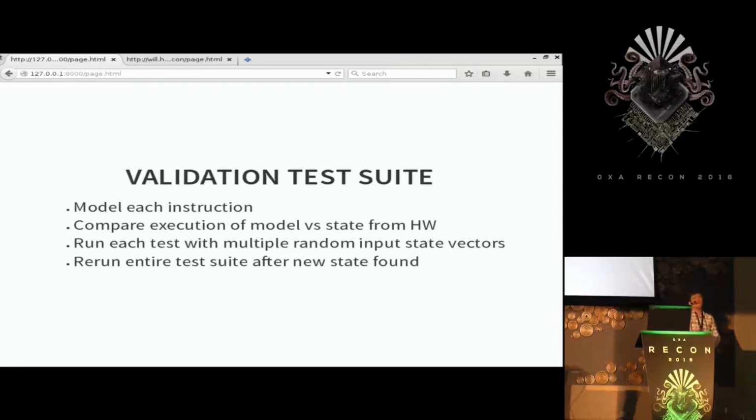So that as you discover new state over time that you don't necessarily know about at the beginning, you can just rerun the entire test bench with that new state being set up to something random and see if your predictions still hold. For example, that would allow you to detect the difference between an add and an add-C. Initially, you might think they're both add operands, but if there's a carry bit that you don't know to set and you find it later on, then rerunning the test bench will identify, hey, I missed something there, and I should go back and check it.